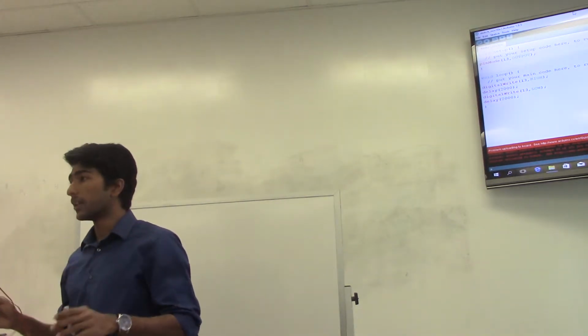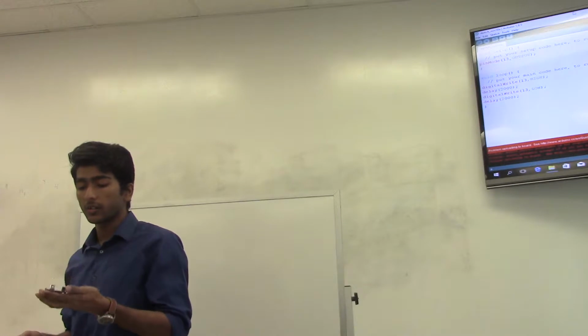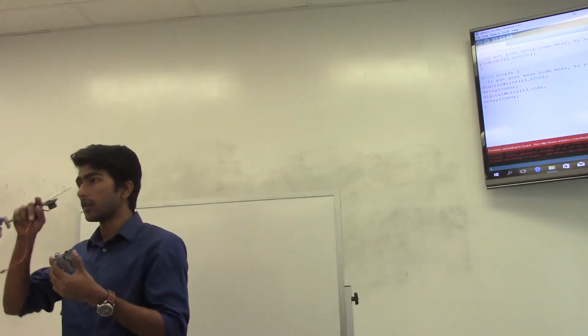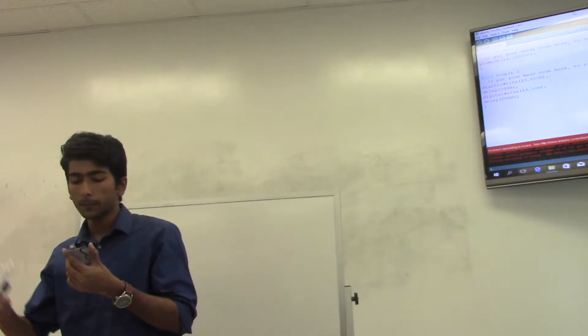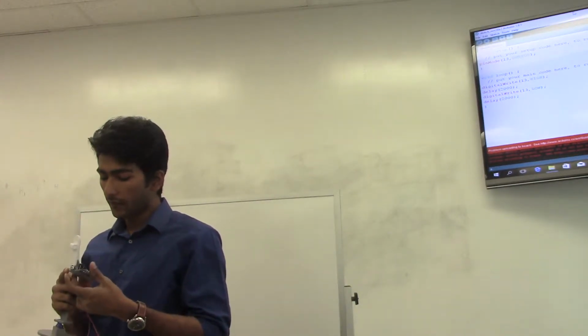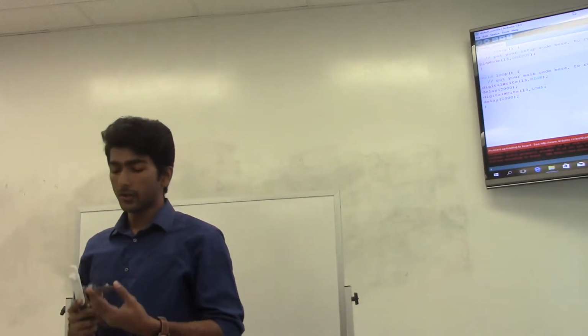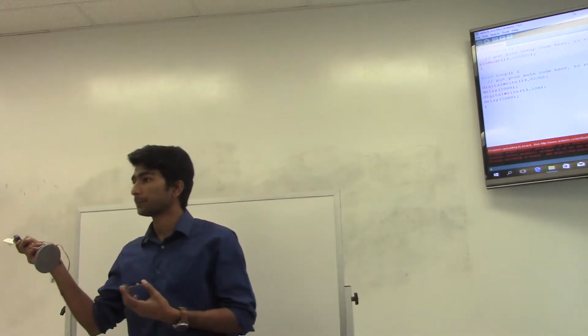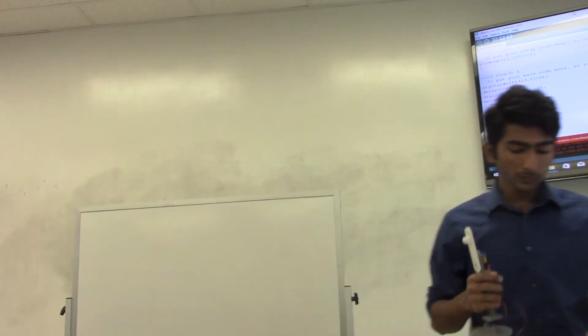I'm not going to go very deep into this, but make sure that you are connecting to any of these pulse width modulation pins. Make sure that there is a symbol, a tilde symbol before the number. In this case we have 11, 10 and 9. So if you connect to, let's say, pin number 12 and 8, these servos won't work. Okay, let's make that clear.